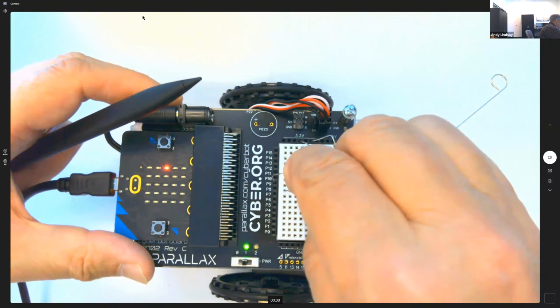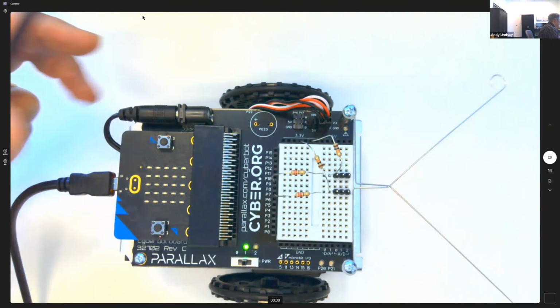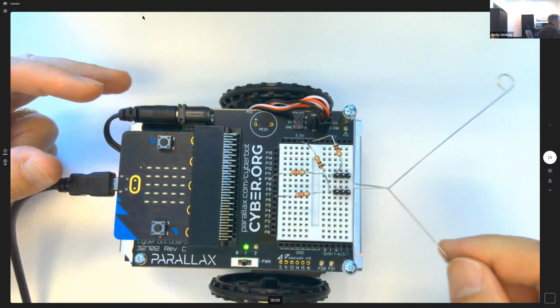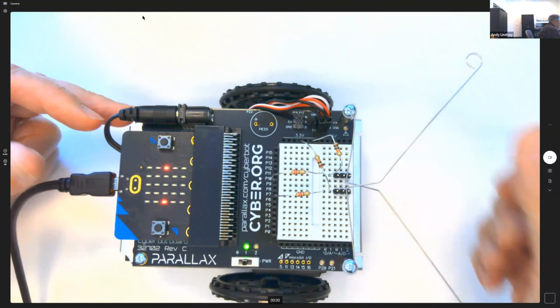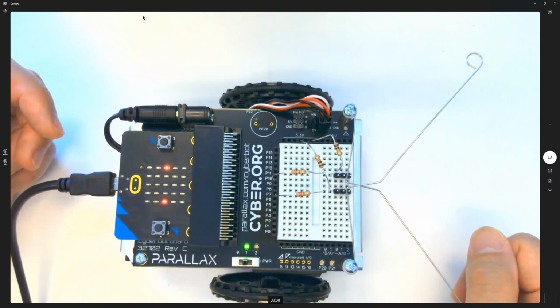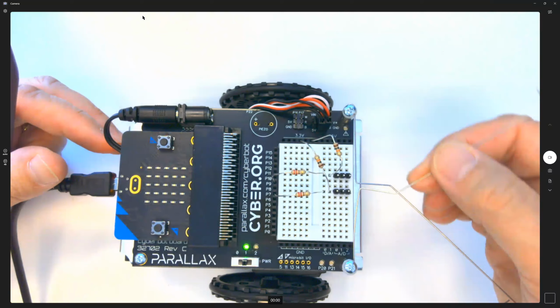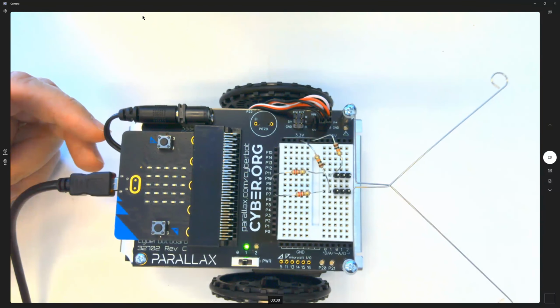So I'm trying to think of what would cause the lights to stay off. It could be that the whiskers are always touching the posts. No, because if they were always touching the post, like if I had the whiskers stuck in between the first 2 posts like that. So maybe the connection to the 3.3 volts is not being made.